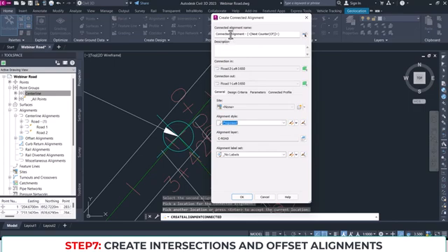So here you can name it. Give it a name, or allow Civil3D to just name it for you. Here we can just call it, let's say, left curb return, because a curb return. So let's see what we have here on the general tab. We can choose a site, but we don't have any site. So we have the alignment style to be proposed. And then the label side, I don't want a label, so good. I don't need labels because the labels are noisy.